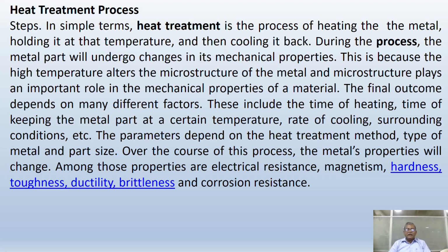This is because the high temperature alters the microstructure of the metal, and microstructure plays an important role in the mechanical properties of the material. The final outcome depends on many different factors that include time of heating, time of keeping metal at certain temperature, rate of cooling, surrounding conditions, etc. The parameters depend on heat treatment method, type of metal, and part size.